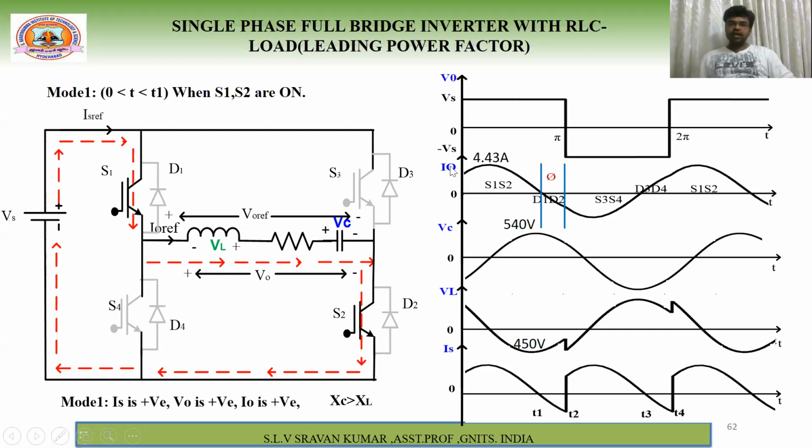First we will see the current and the voltage across the capacitor. What is the phase difference? Just now I told you, 90 degrees. Whenever the current is maximum, the voltage is zero. That is the 90 degrees phase shift. Next, again the current is negative maximum, and the voltage is zero. Again here, the current is zero but the capacitor voltage is maximum. So with a 90 degrees shift, you have to draw a sinusoidal voltage waveform, and similarly for the current, exactly a 90 degrees phase shift.